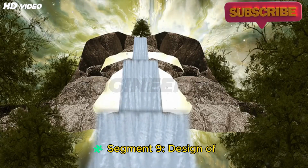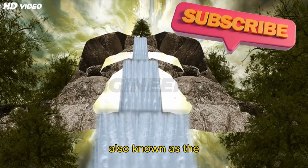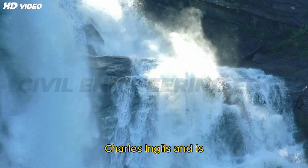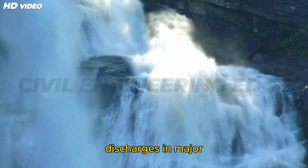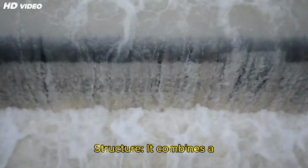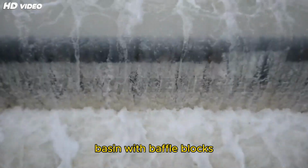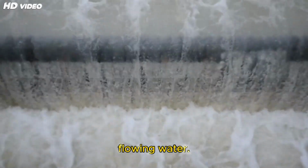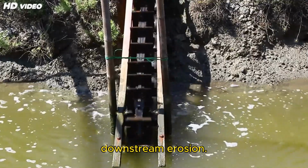Segment 9. Design of a baffle fall or Inglis fall. The Baffle Fall, also known as the Inglis Fall, was developed by Sir Charles Inglis and is suitable for high discharges in major irrigation canals. Structure: it combines a glacis and a stilling basin with baffle blocks or teeth, which absorb the energy of fast-flowing water. This controlled hydraulic jump reduces downstream erosion.